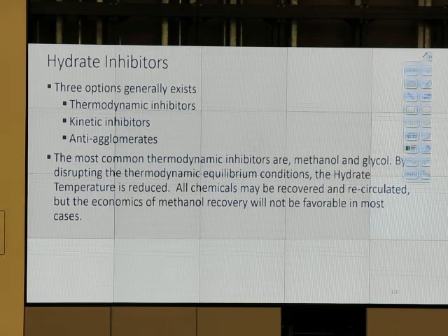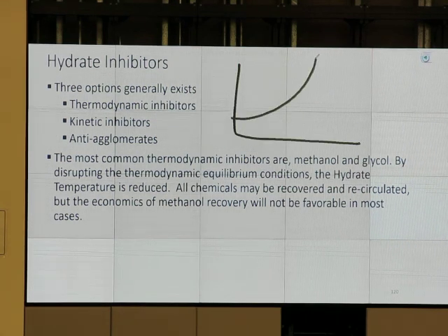But to be correct, technically you say it is thermodynamically stable for hydrate to form. Okay? It may take some time to reach the thermodynamic equilibrium, but at equilibrium, the hydrate forms. For example, it can take 10 minutes for hydrate to form, even though the condition is preferable for hydrate to form. Good?